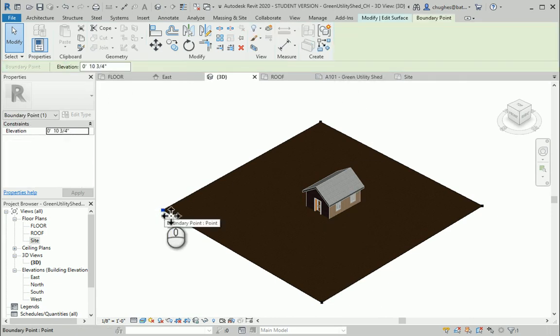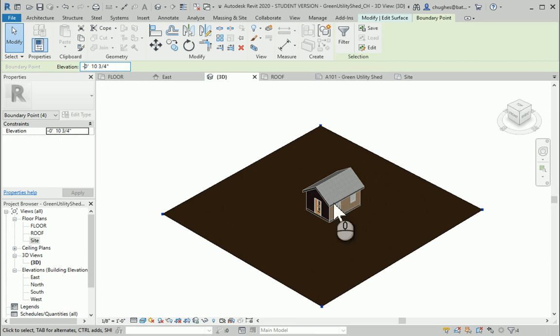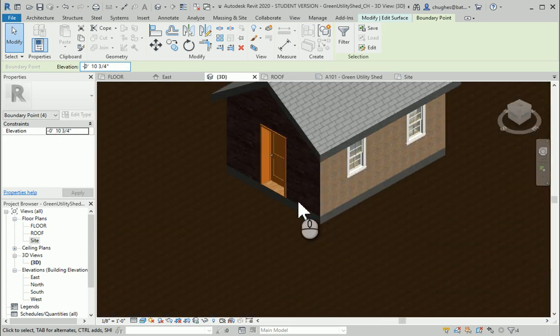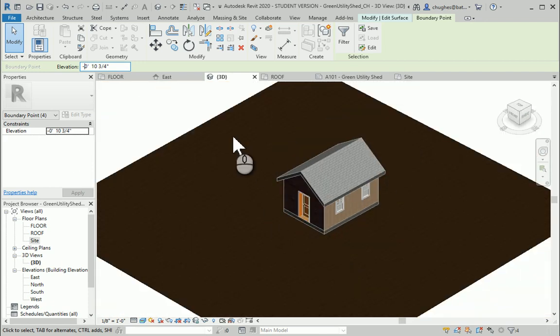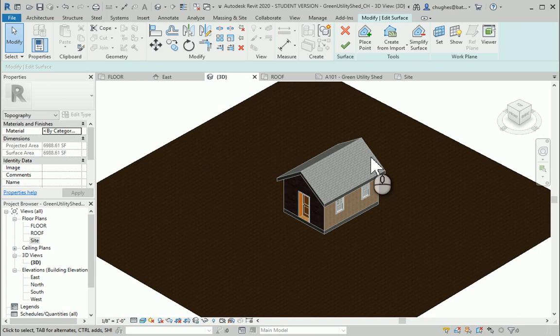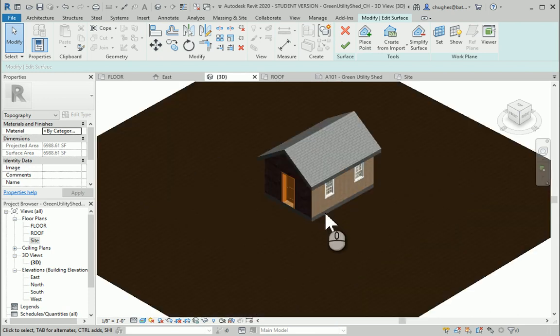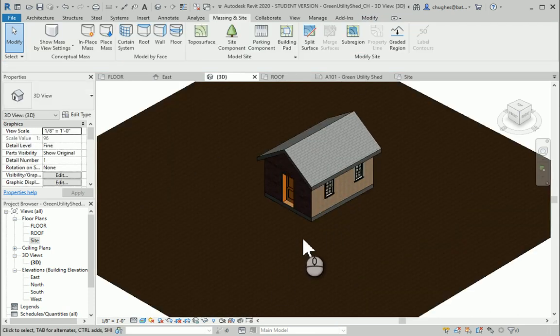It looks like I do need to hold control. Let me select all 4 of these again. So it bumped it up. The negative has to go before the 0 feet. There we go. Now we're seeing our floor properly, as we should based upon the elevation. Once I'm done with that, I can just click out of the elevation option and click the green check mark.